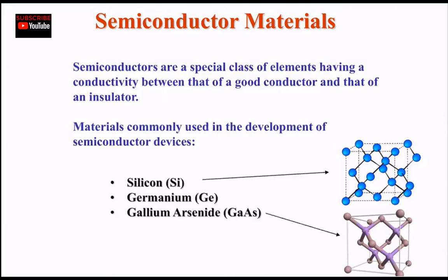We learned about light dependent resistors. We did a couple of experiments on it too. What was the relationship between the light intensity and the light dependent resistor? When the light intensity increases, it actually decreases the resistance of the light dependent resistor. So there was an inverse relationship between the resistance and the light intensity.